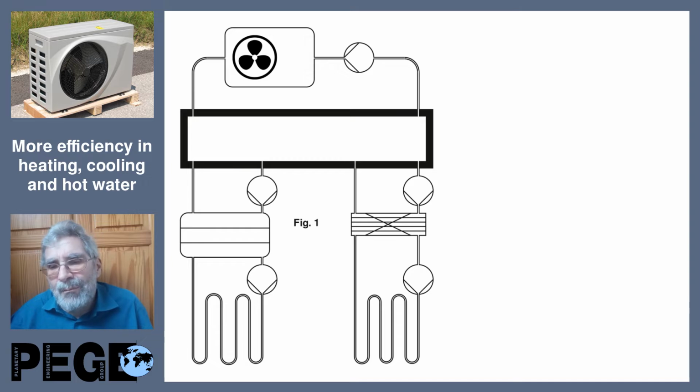And at the low temperature heat storage, we have a water-to-water heat pump for floor heating, for domestic hot water, and also we can use directly the heat of the low temperature heat storage, with a plate heat exchanger, for other applications which need only low temperature.